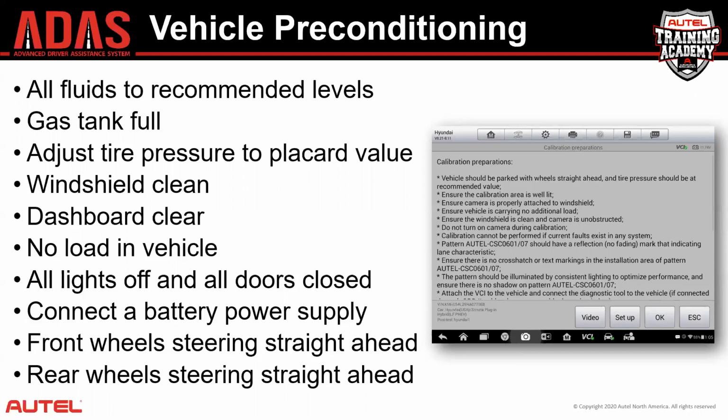So many of these things, like for instance, you've got a vehicle coming into your shop, you're going to be performing a calibration, you just let the consumer know: make sure the gas tank is full and there's no extra load in the vehicle before you bring the car in. That way you won't have to worry about it. Same thing with a contractor. These aren't optional steps. These are all absolutely critical to the accuracy of ADAS calibrations.